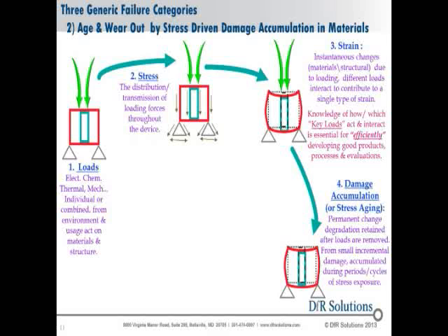And if you take it out to that extreme load again, you're going to get another reduction in its return capabilities. And that is because we are doing molecular damage when we take it out so far that we break molecular bonds inside the material and we start to weaken the device. So this is what we mean by damage accumulation, or stress-driven aging.